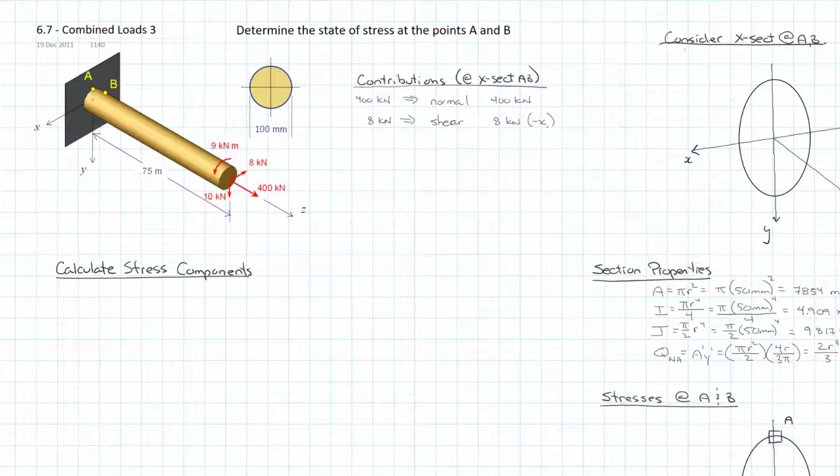And it also provides bending about an axis at the AB, right? Because we have that moment arm, perpendicular distance, if you will, from that plane to this plane of 0.75 meters or 750 millimeters. So it would cause bending, and in this case, that would be bending about the y-axis, bending about y.